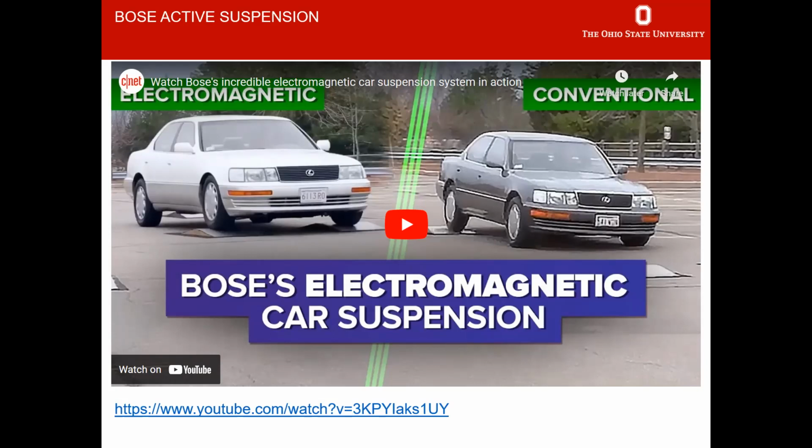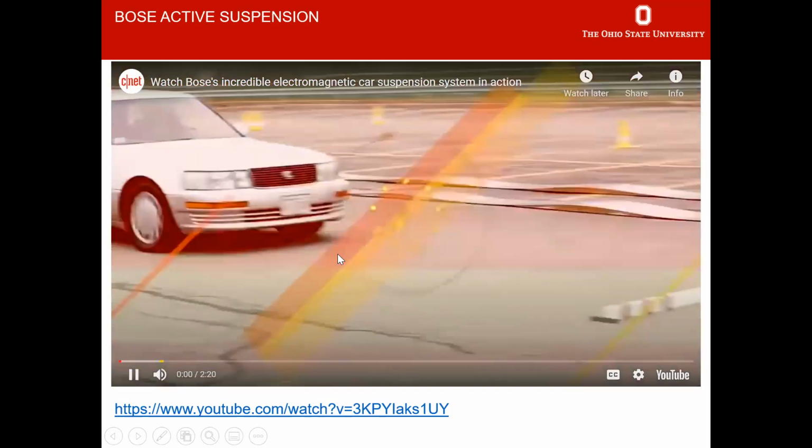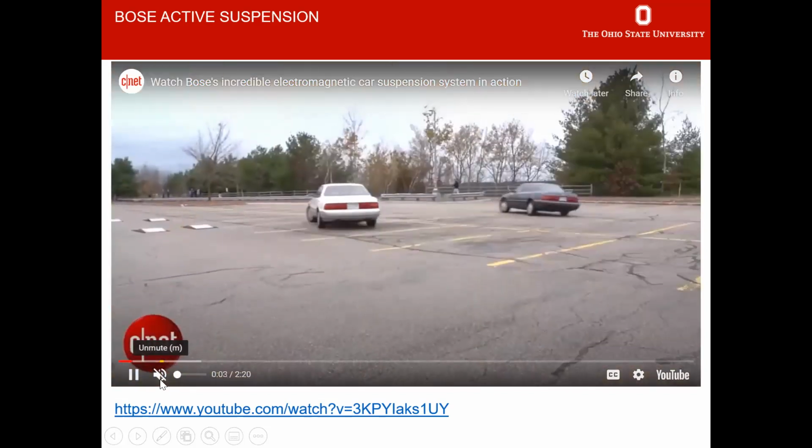Active suspensions have been around for a very long time, and they are a closed-loop control system. The output variable is acceleration, and we did take a look at an example on this. It's mostly acceleration at the body, so you put accelerometers there. We have some nice examples of semi-active suspensions because they are cheap. Active suspensions are available in some expensive cars, but people don't really care so much about them to pay the extra. So that's why we don't really have these in series production cars that we can all afford.